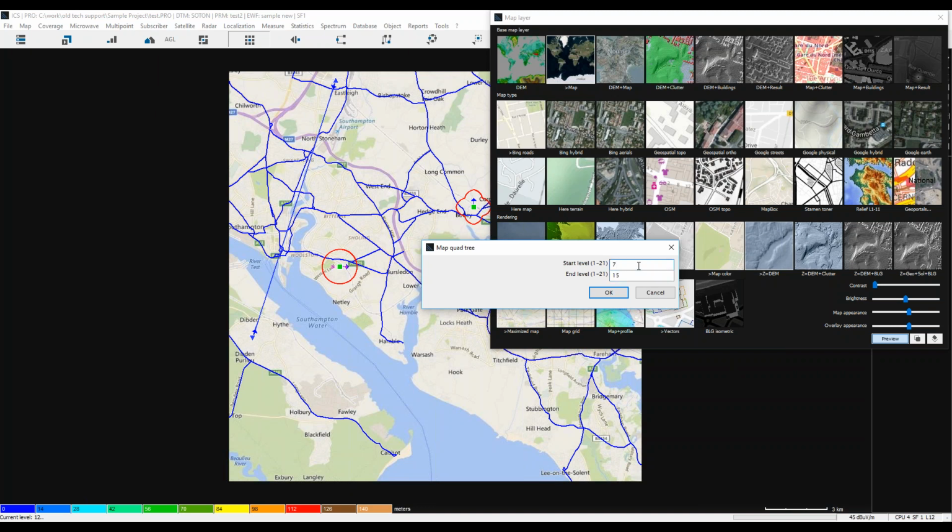Now, just a note of caution, if you're going for lots and lots of levels, for a large area, it's going to take quite some time. So it's probably most useful to do it for the levels that you're going to have. The higher levels, the sort of 7 and above, are a relatively small number of tiles anyway. So it's perhaps most advantageous when you're getting down to lower levels of resolution anyway. So that's where you access that function from, and then that will go away and place it into the map cache area that's within your Bing Maps license file.